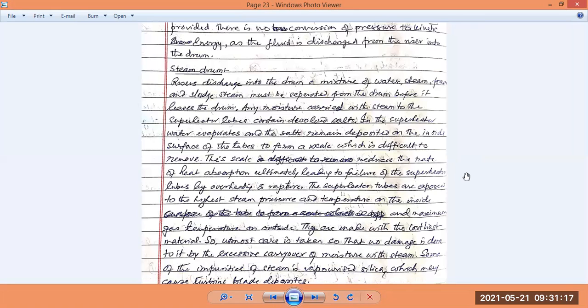So you have to avoid depositing this inside the boiler wall, because what will happen? This deposit on the wall of the superheater will prevent the heat coming from the flue gas from reaching the boiler water itself, because the coating itself will get heated and absorb the heat, and it will take much more time for the water inside to be superheated than with a clean superheater.